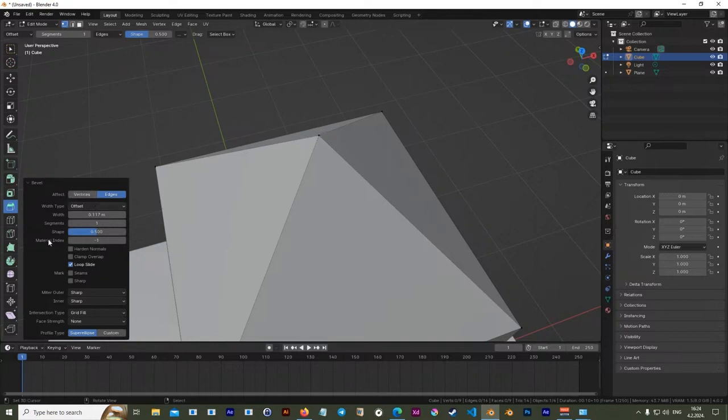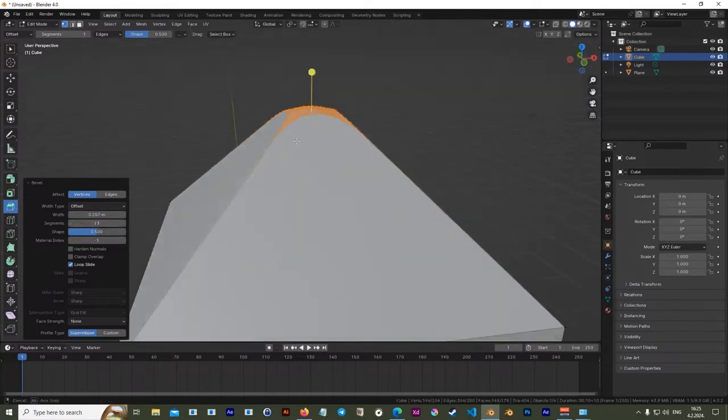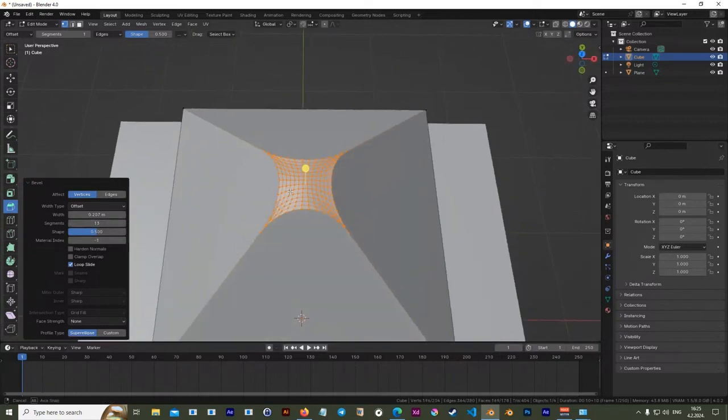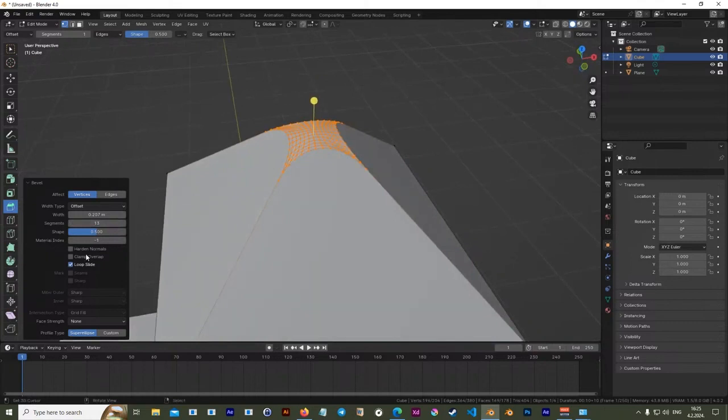and the most important thing for you is to get to this bevel line. Here you can press vertices, and now you can bevel your vertices as you like. You can also add segments, which will smooth this bevel, and it's really nice.